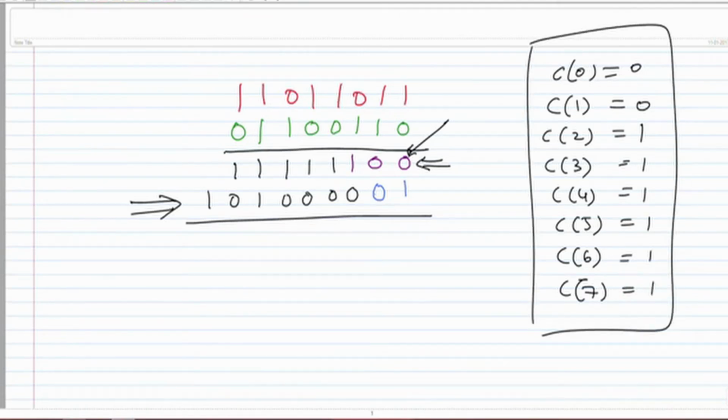If I know the carry at the earliest, I can immediately compute the sum bit, because Si is nothing but Ai exclusive or Bi exclusive or Ci minus 1, correct, or Ci in this case, because in our terminology we say this is 0, this is C0, and this is A0, A1 and so on till A7, and this is B0, B1 to B7, okay.